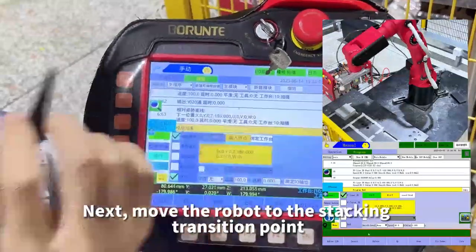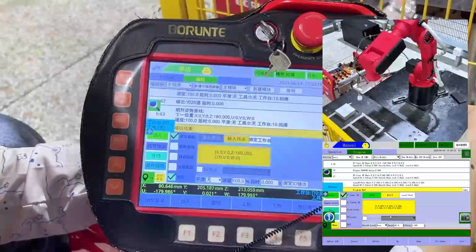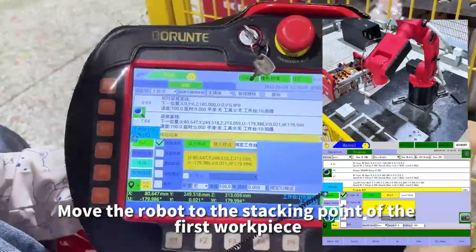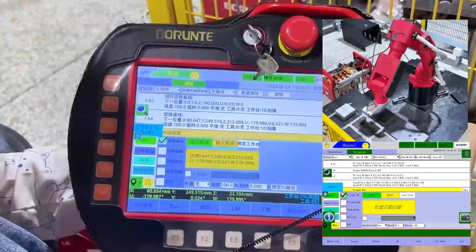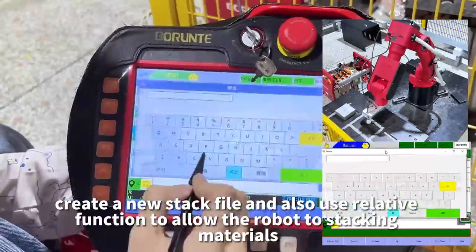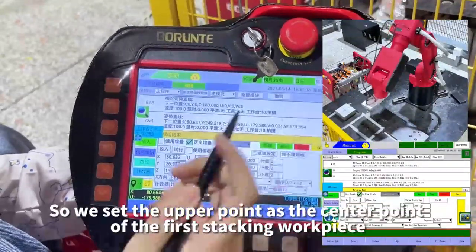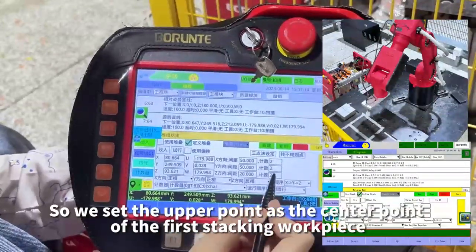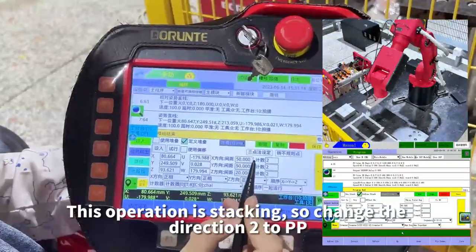Next, move the robot to the stacking transition point and repeat the previous operation. Move the robot to the stacking point of the first workpiece. Create a new stack file and also use the relative function to allow the robot to stack materials. So we set the upper point as the center point of the first stacking workpiece. Click Insert. This operation is stacking, so change the direction to 2 PP.